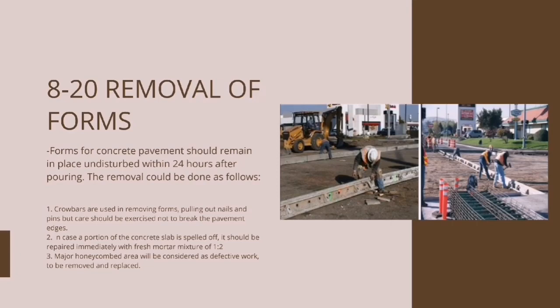Second, in case a portion of the concrete slab is peeled off, it should be repaired immediately with fresh mortar mixtures of 1:2. Major honeycomb area will be considered as defective works to be removed and replaced.